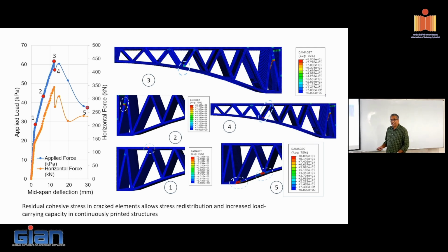The bottom arch fails at compression. You have a compression failure there, that leads to a failure of the structure. So failure is driven by compression of the compression strut. The most heavily loaded compression strut is the bottom arch here. Right? So that's what fails, and that produces the maximum load.